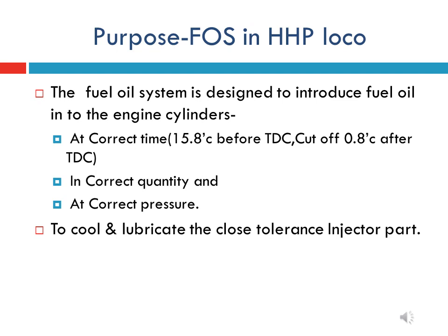The fuel oil system of HHP locomotive is responsible for supplying fuel to the diesel engine in the correct quantity at the right time according to engine requirement. In this system, the fuel oil also plays a vital role, and it cools and lubricates the internal parts of the unit injector. So it is to be kept in mind that internal parts of mechanical unit injector in WDG4 or WDP4 locomotives are cooled by excessive fuel oil.